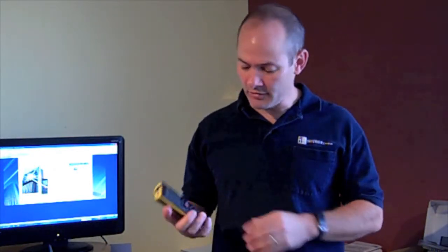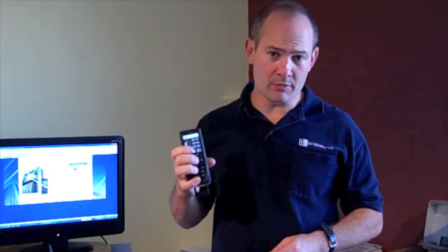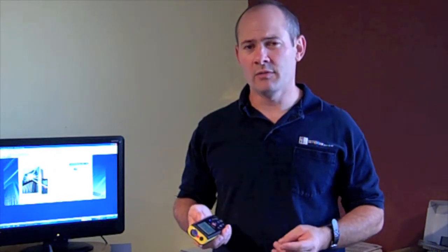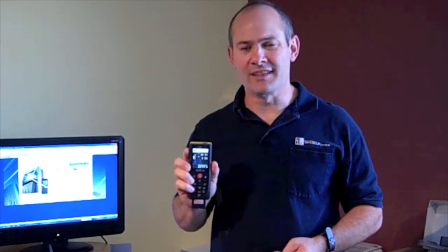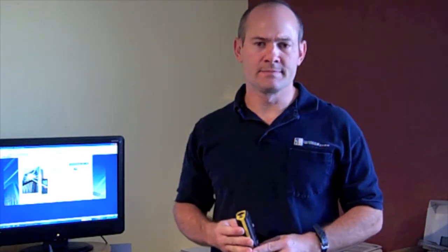Another excellent feature of the disto is its ability to measure a minimum and maximum point from any reference point. In order to do that, you just hold down the red measure button and it will scan across a wall into a corner, allowing you to get maybe the maximum or minimum measurement that you need. In this case, when we're measuring into corners, we're looking for the maximum distance from any reference point, and with this function it allows us to get it easily and quickly.